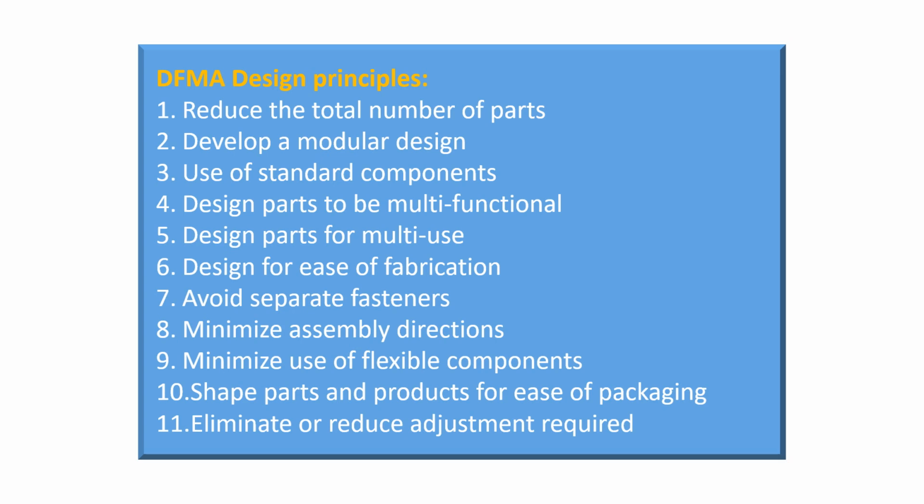5. Design for ease of part fabrication. Net shape and near net shape processes may be feasible. The geometry of the parts is simplified, and unnecessary properties are avoided. Unnecessary surface treatment requirements should be avoided, otherwise, further processing may be required.